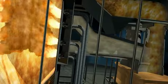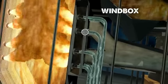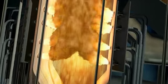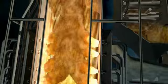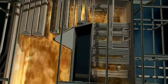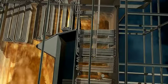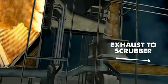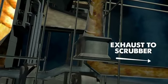The hot forced air and coal dust converge in the windbox, where the mixture is blown out through burners and ignited inside the firebox, transferring radiant heat to the water-filled tubes. The hot gases flow upward, heating the rest of the system through convection, before passing through the air preheater and ultimately flowing into the scrubber, where pollutants are removed.